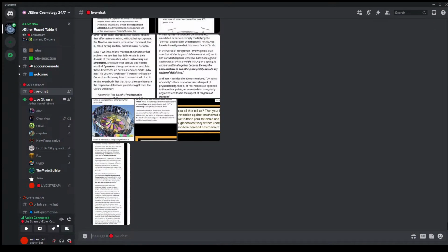But as soon as you put some force on the mirror, even the slightest one, you will displace the mirror. Even a slight displacement will create what we call a fringe shift. So the fringe that is displayed will move, and this move is in perfect correlation with the displacement of the mirror. So you can use it to measure things.